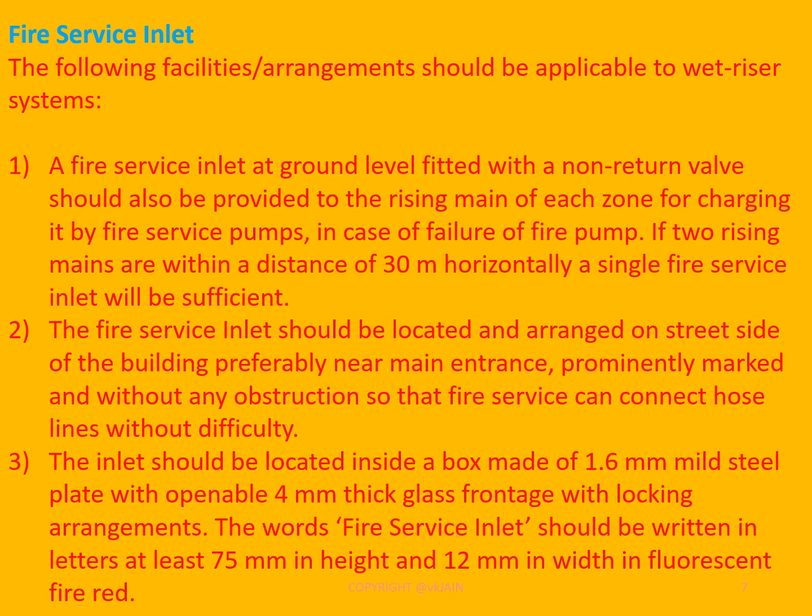A fire service inlet at ground level fitted with a non-return valve must be provided to the rising main of each zone for charging it by fire service pumps, in case of failure of the fire pump. If two rising mains are within a distance of 30 meters horizontally, a single fire service inlet will be sufficient.